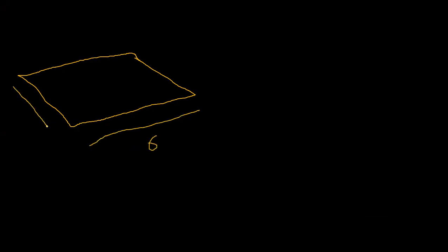I didn't model the slab. My span, if I select one particular panel, was 6 meters and this was 4 meters. So this is Lx and this is Ly. I need to determine whether this is two-way or one-way.